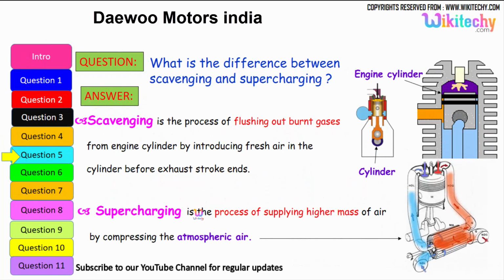Let's move on to the different question. What is the difference between scavenging and supercharging? Scavenging is the process of flushing out the burnt gases from the engine cylinder by introducing fresh air into the cylinder before the exhaust stroke ends.